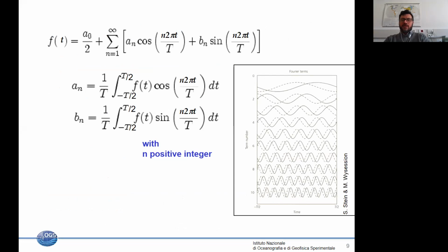And here, I just show an example. So in this case, you see we substitute the integral with a summation. And the Fourier transform of this signal can be described as the summation of many discrete terms depending on the cos term, again in principle for different frequencies, for different periods, and the sine term representing the real and the imaginary part of the signal.